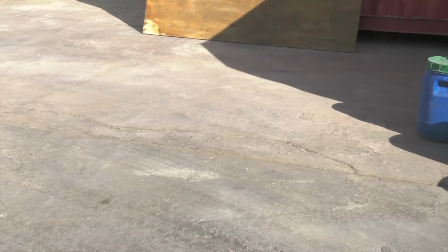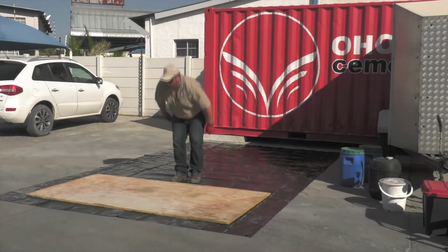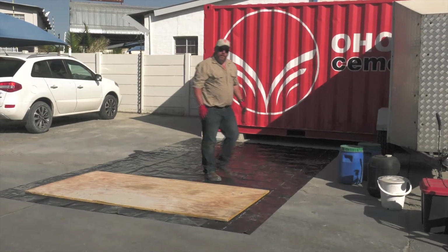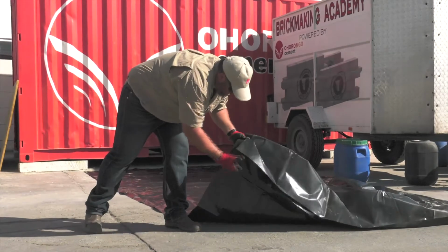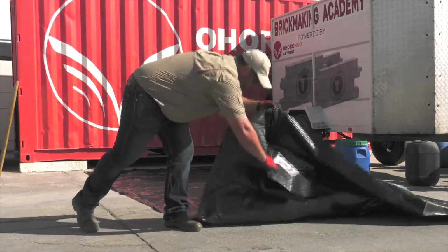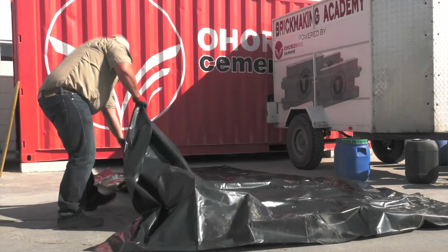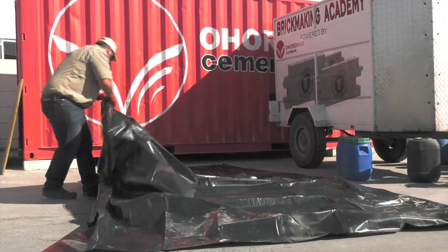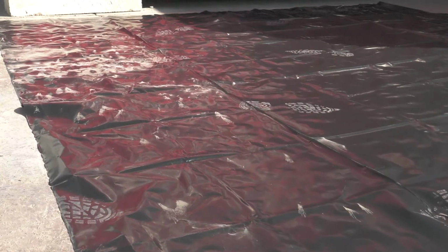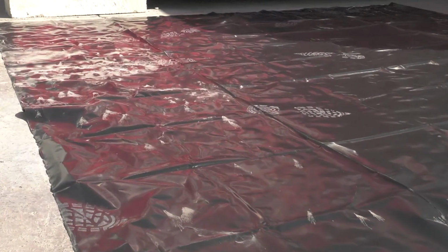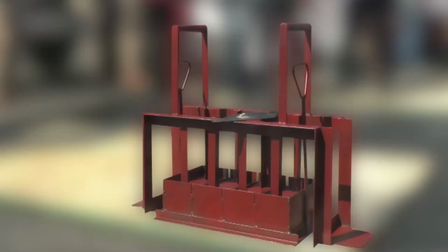You require a hard surface to mix the mortar. For example, you can use a shutterboard. Then you require an additional hard and even surface where you're going to mold the bricks. This area preferably needs to be in the shade. If not, you would be required to cover your bricks for the first day. You require plastic sheeting to place below the bricks you are going to manufacture. This is not a requirement, but it is advisable. Last but not least, you require a brick mold.